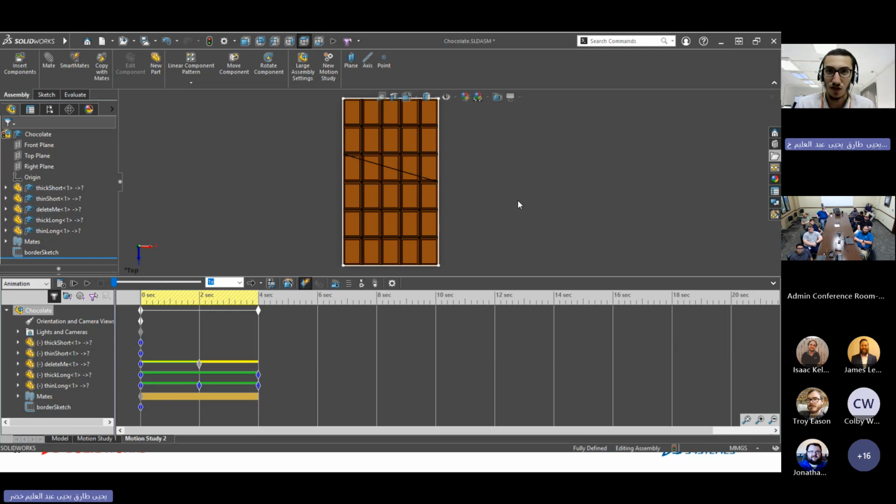And in that case, I'm going to have some interference. So what I wanted to do is actually to pause for a second until this first part is cleared all the way down out of the way, and then it should start to move to the side. And I know that that part is going to finish at the 2-second mark. So what I want to do is just make this not start from the 0-second mark, but actually from this 2-second. And that's as simple as just dragging this from here and releasing it at the 2-second.